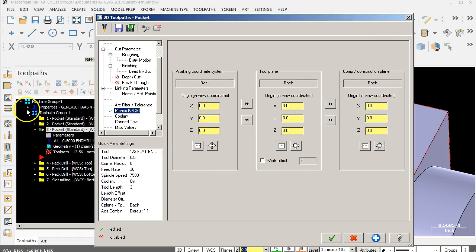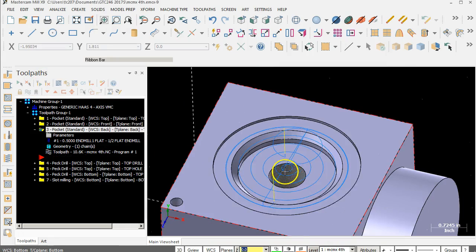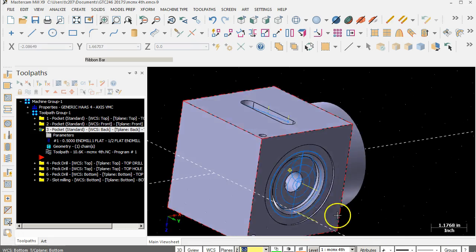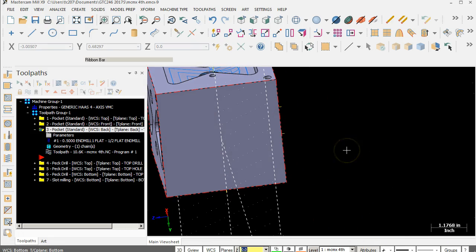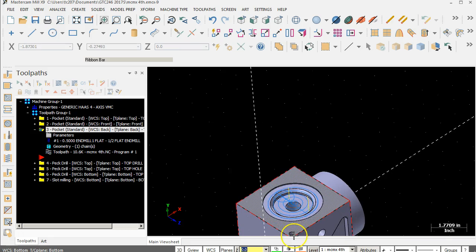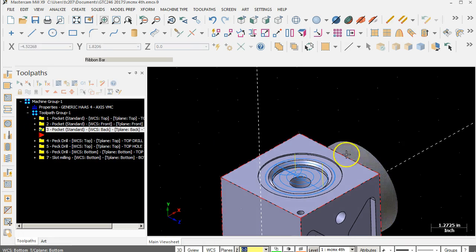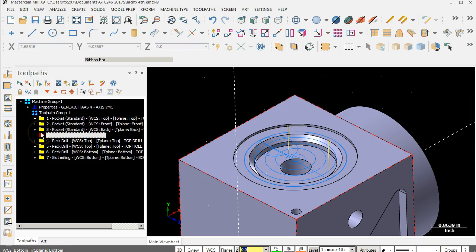So in that respect, it is probably going to be better to go ahead with all of the operations just as if this was a 2.5 axis, and then sort for the common tools after we've gone through the complete part and make sure that the index is happening correctly. And that's going to do two things: make sure, oh, I didn't switch over to the bottom, so I guess that isn't as critical anyway. That may have been where I lost my frame of reference though. All right, so let's go ahead and paste.